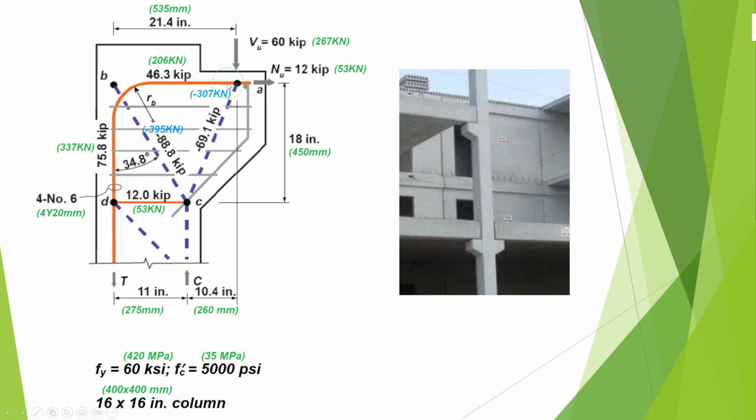internal forces of the strut and tie model. Normally the ACI code provides two methods to calculate or to design the corbel. One method is simplified with certain conditions. You have to meet them first. And the second, general method can be used for all cases of corbel, strut and tie. This is strut and tie. And these struts and this tie and this also tie. Here we have horizontal tie and vertical tie, and we need to satisfy the anchorage requirement using curved bar node provisions.